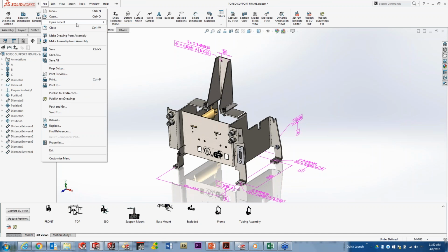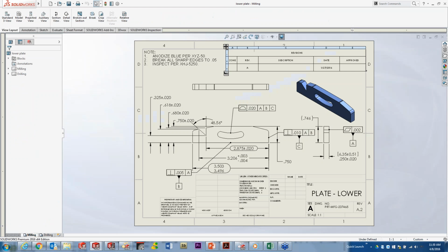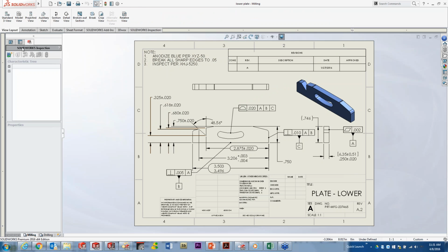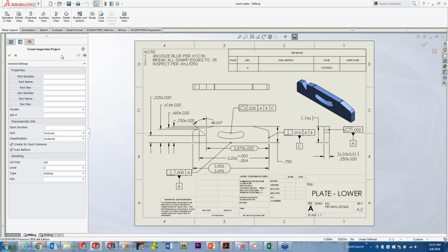With SolidWorks, we open up your SolidWorks native drawings. And of course, a SolidWorks native drawing is going to have intelligence to it. We're aware of the dimensions, we know where they are, we even know where the notes are. So to do the capture process inside of SolidWorks, it's really just a very simple 3-step process. We use a template that's going to have some pre-set up logics and defaults. We have several that come with the software.